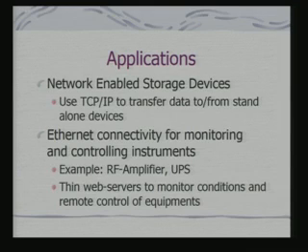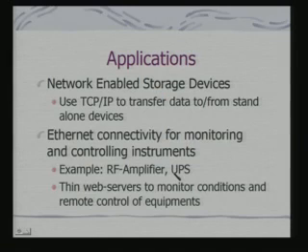And another example is a UPS, if you want to monitor the battery life of a UPS remotely. So, what you provide? You provide a TCP IP as well as Ethernet enabling feature. In fact, if you remember, we had seen an example of a vending machine which is Ethernet enabled, so that the complete stock monitoring can be done from a remote location. In fact, on these devices, if they are really implementing TCP IP, on top of TCP IP you may find thin web servers, very basic web servers implemented. And why web servers?